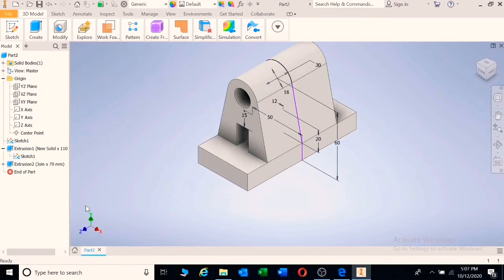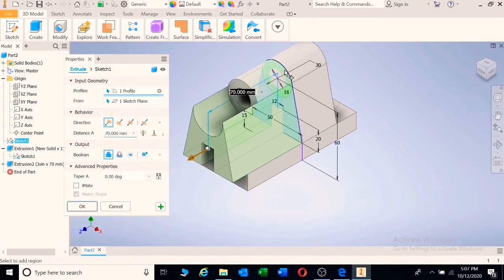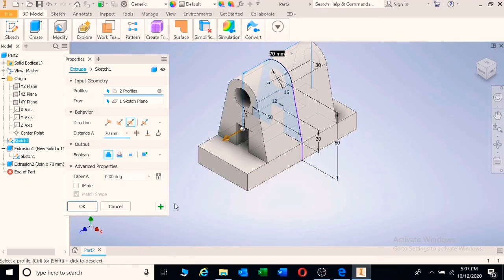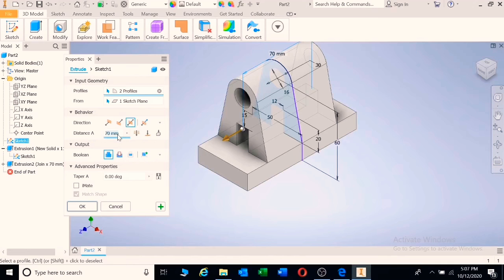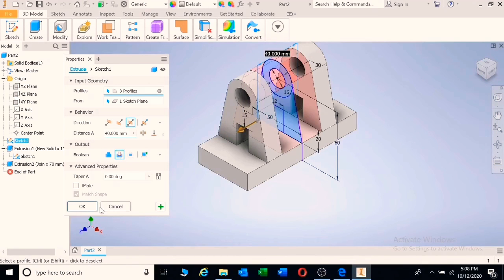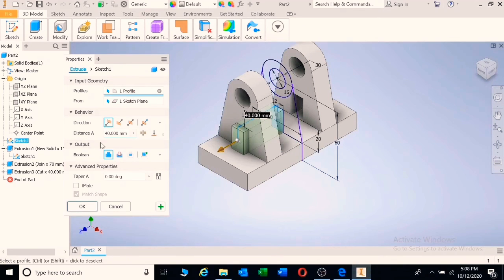And we're going to say OK. Let's say if we extrude again, and we're going to do a cut. Select the very same surfaces and double, and we know that the center there is 40, and we're going to type in 40 there. Say cut. There we go, guys. We're going to extrude again when you go all the way out by 70, which is all the way, plus 20 on both sides, which is 40. My 0 is a little bit stubborn. And there we have that on both sides, and say OK.